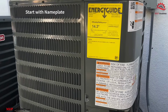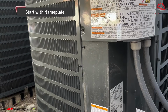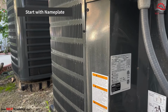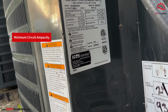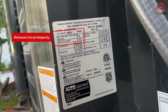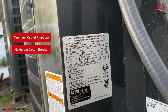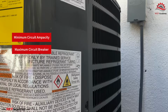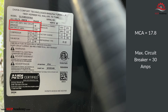Always start with the nameplate. The most important rule in sizing conductors for an air conditioner is this: you always start with the equipment nameplate. Every listed air conditioning unit is required to have a visible nameplate that provides the electrical information you need. The two key values on the nameplate are minimum circuit ampacity, commonly labeled MCA, and maximum circuit breaker or fuse size, sometimes labeled MOCP. These values are provided by the manufacturer and already account for motor characteristics, starting current, and internal loads. If the nameplate gives you these values, your job is not to recalculate them. Your job is to verify and apply them correctly.